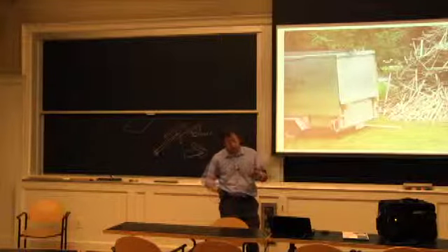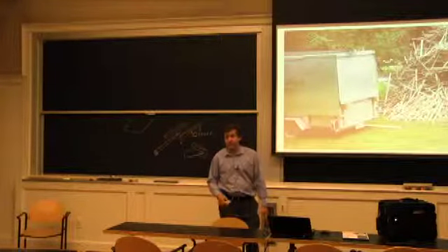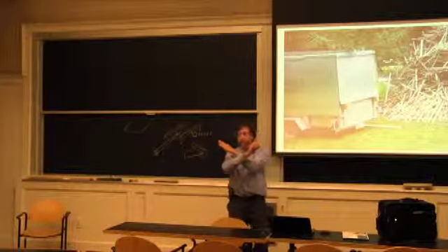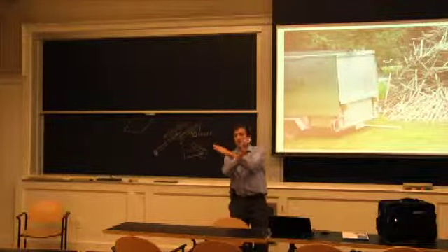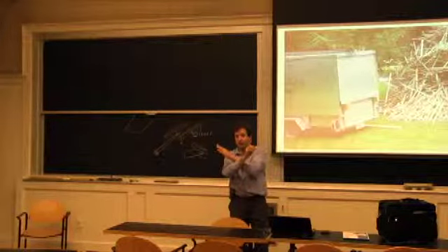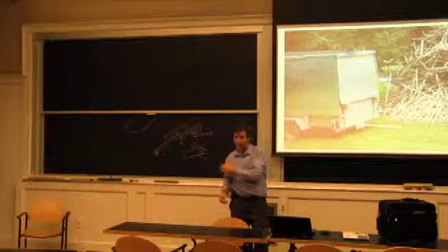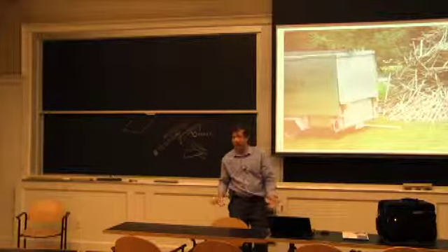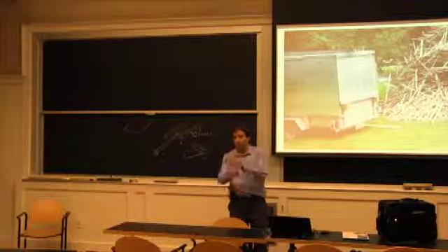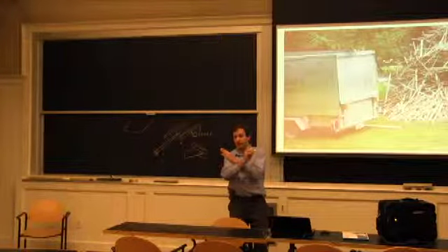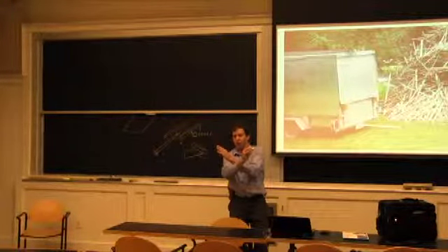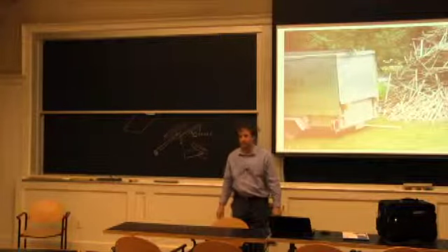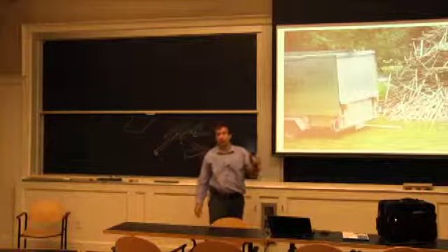It's stronger in strength, but it's still a relatively flexible structure, and that's why it also has a cross member two-thirds of the way, so there's no issue of side forces, which are a little bit like the lower frame. How much side forces are you going to have? You don't know. So there's a cross member at the beginning, and at 1/3, and the door in the back also prevents racking, the same type of twisting of the overall fuselage.